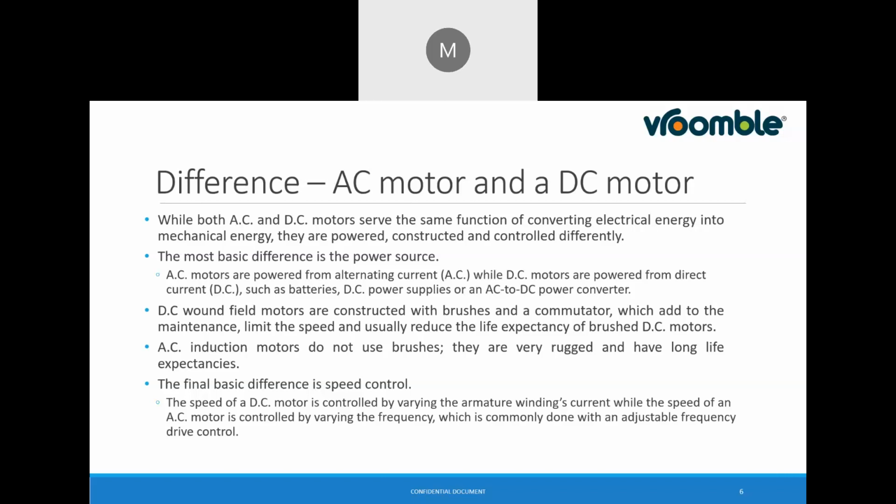Mainly, the main components are the rotor, stator, and the motor body. But for example, I would like to tell you about the hub motor which we have seen in two-wheelers. That motor is called an outrunner, right? So the rotor is outside and the stator is inside. The shaft is static, or steady, because it is coupled with the swing arm of the vehicle, and because the wheel rotates, that means the rotor is outside. So that is known as an outrunner motor. Otherwise, where the shaft is rotating and the rotor is inside, that is known as an in-runner motor. But again, that can be AC or DC, anything.